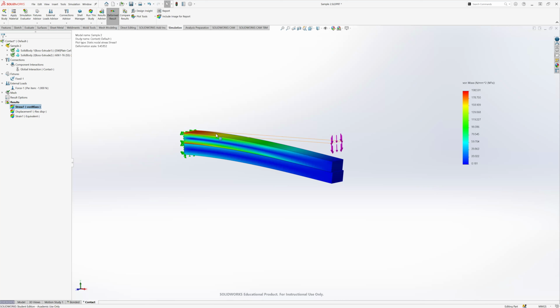Single part, single body, multi-body, composite. Again, just make sure your contacts are right, make sure your constraints are right. Again, that's something that comes with practice. So you just kind of imagine in your mind what you would think it's going to do in real life, then try to simulate it and see if it's giving you that correct behavior or the behavior you're expecting. If it's not, then try to figure out, is the simulation correct or are you correct, and adjust from there, until you can get the behavior that you're expecting. Okay, any questions on interactions or anything?